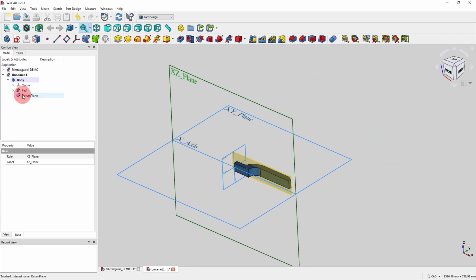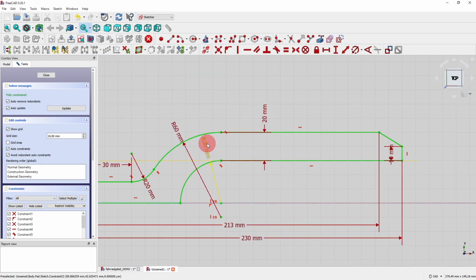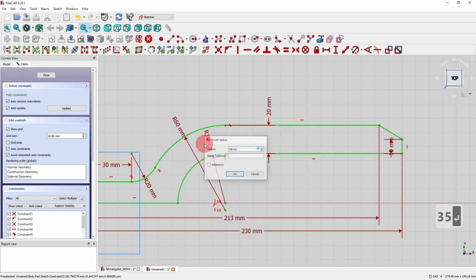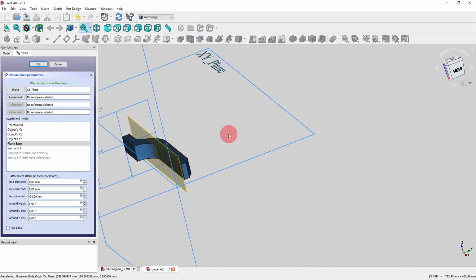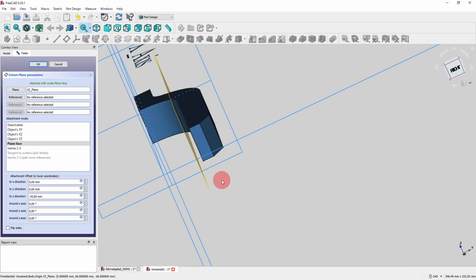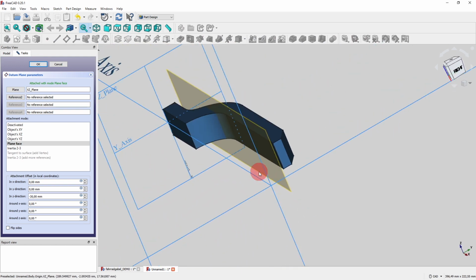If we change the basic geometry here in the first sketch, as you see, like we have now 30 millimeters, let's set it to, let's say 35 millimeters. Happens from time to time that you have to make changes to your model. And now you see the datum plane is no longer on this face here. It's floating a little bit in front of it, 5 millimeters to be exact.